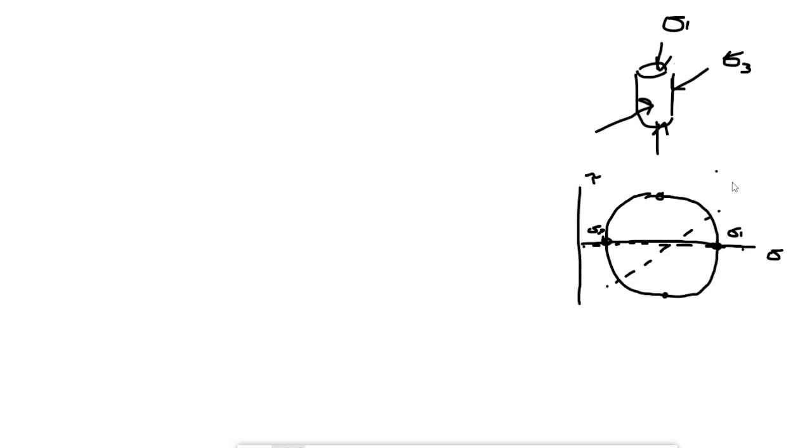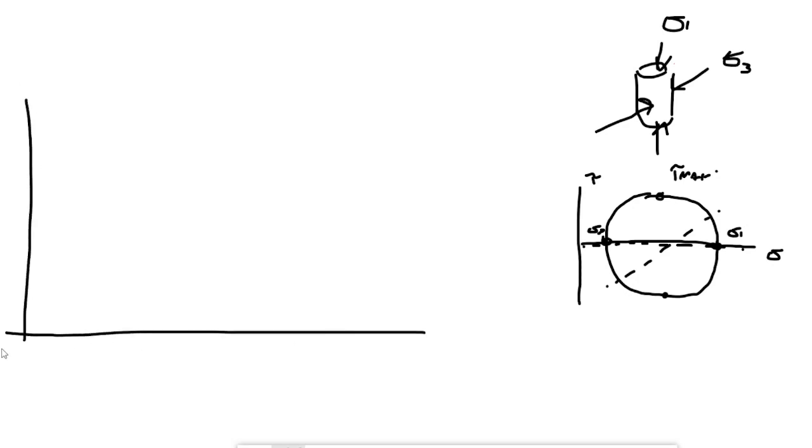So this is where it gets relevant, because up here at the top of the Mohr circle, you'll know this is where we have tau max. And of course, it's symmetrical about the x-axis, so you'll have another tau max here, just in the opposite direction, right? The magnitudes are going to be exactly the same. So that's important. What is that tau doing? Well, let's bring a picture over here, and this is going to be a plot that is derived from the results of the previous plot we made.